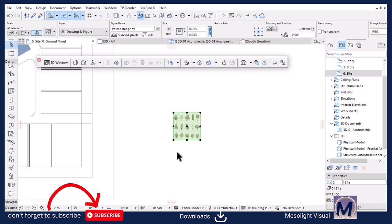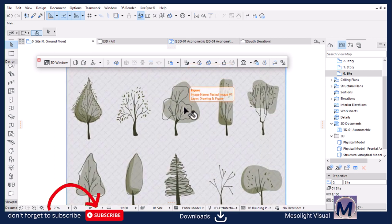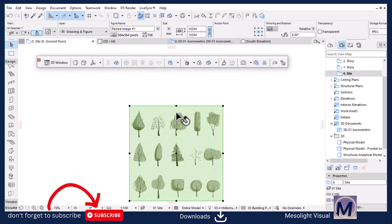So let me just do this. I'm going to press Control K to scale this. Oh no, you know what? Let me scale to reference. I want the height of this to be maybe 3 meters, for example. Control K, and then from here to here is supposed to be 3.5 meters.